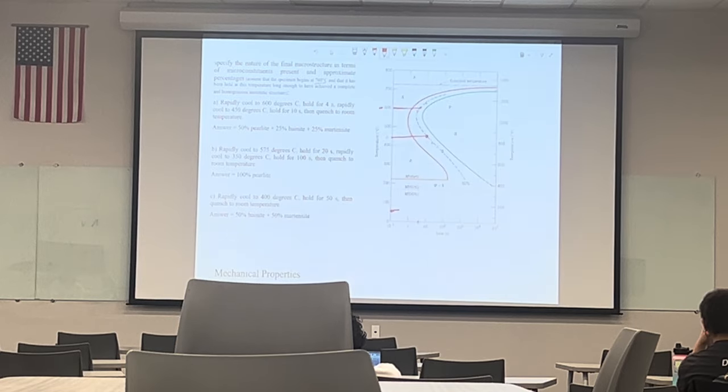So whatever turned into pearlite, we just put it aside. We're not going to use that anymore. I mean, pearlite is just stable. It's not going to change anymore. So for the remaining steps, we're going to just focus on the remaining austenite. So in this case, in the first step, we lost 50% of austenite. Not lost, but 50% of the austenite turned into pearlite already.